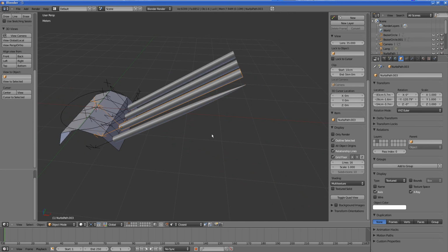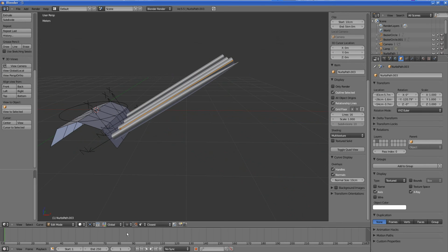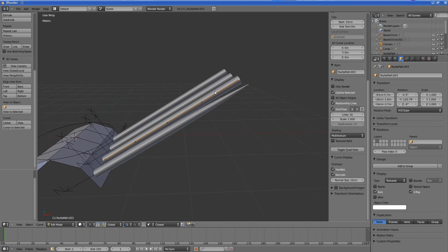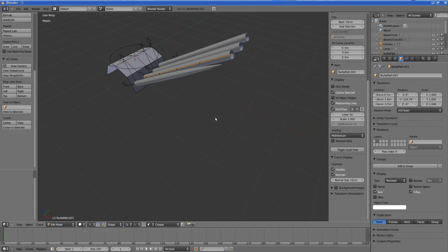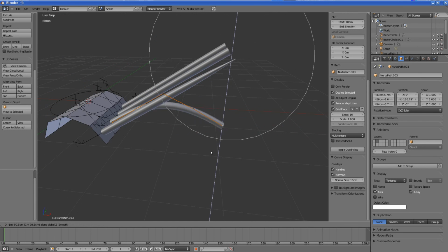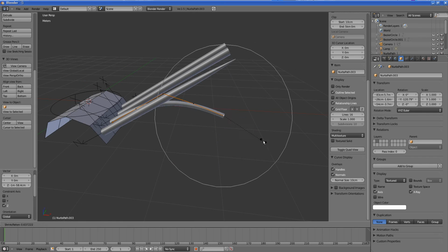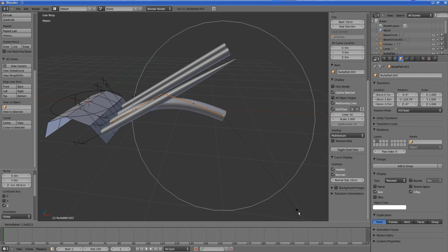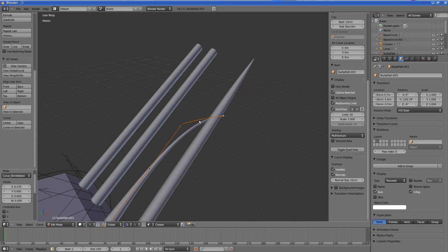Okay, we can also make use of proportional editing. Okay, let's turn off snap for now. Let's enable proportional editing. Select this vertex and move it. Okay, so there you go, move it in the Z direction. Okay, Alt S. Now when you do Alt S, because we are in proportional editing, whichever control vertices fall inside the circle will accordingly shrink and flatten.